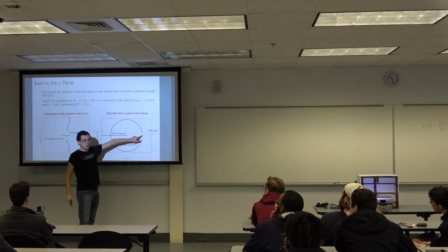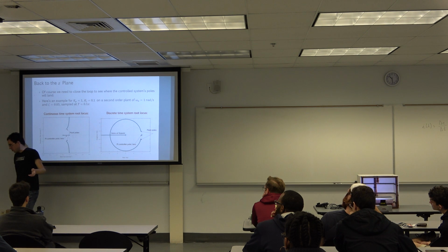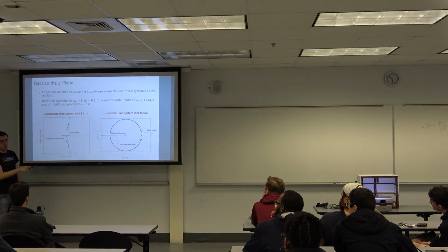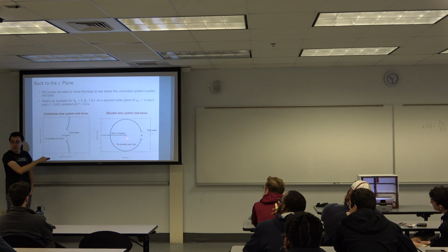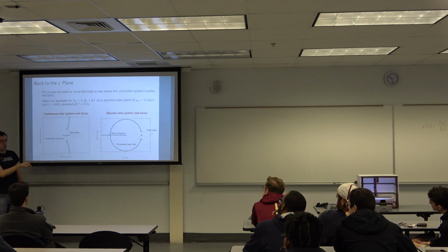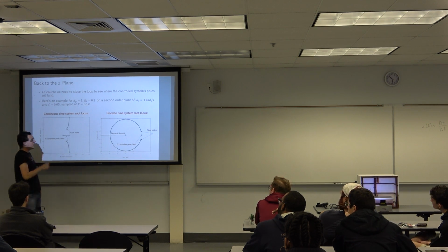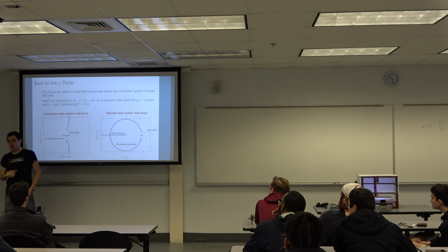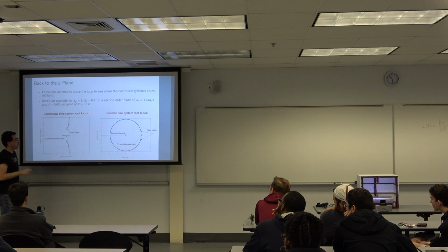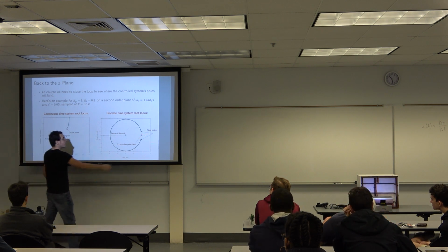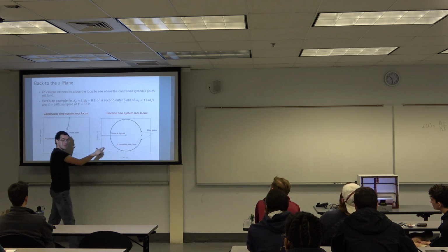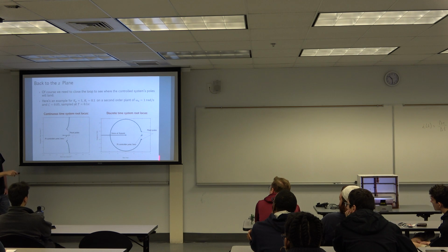But if we use the same plant, so now the plant poles are sitting here, and the zero and the pole of the controller are sitting here, the discrete version of the plant will have zeros at Nyquist. Maybe Dr. Hubicki is going to cover that in the future. So one zero goes to the Nyquist and the other goes to infinity. But this dashed circle is the stability bound. Everything inside the circle is stable. So the poles of the closed loop system, which started in the stable region, now become unstable. So our discrete controller can destabilize the plant by virtue of discretization.